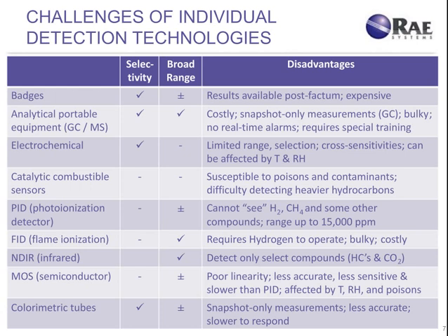Now, electrochemical sensors are very, very broadly used across different industries for gas detection and personal protection. Such sensors are usually selective in nature. They have limited range. They usually don't go into very, very high ranges. There is a limited selection of such sensors available, even though it's getting wider and wider. But there are substances like benzene, for example, for which there is no electrochemical sensor available.